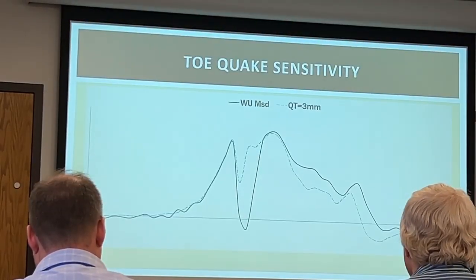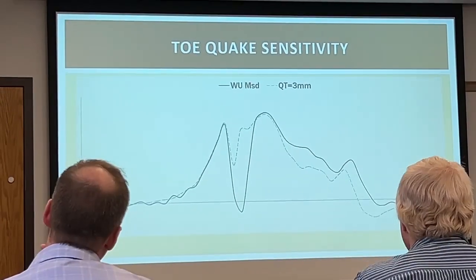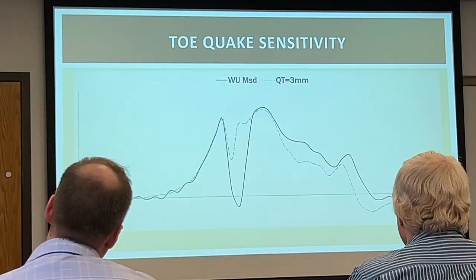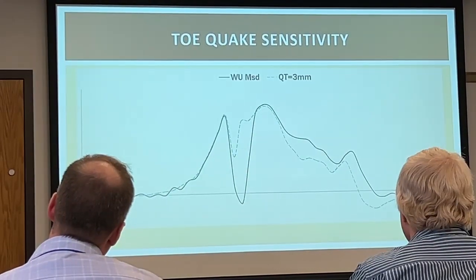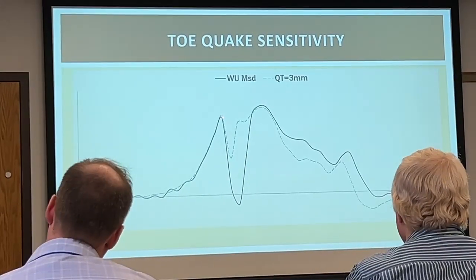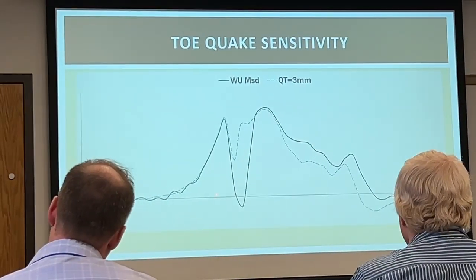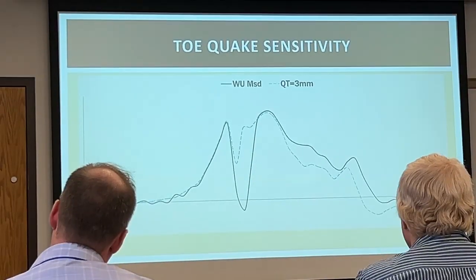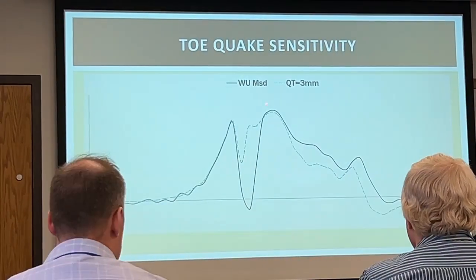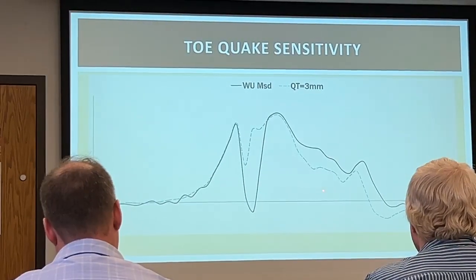So if we are looking at a wave up, remember, quiet period is either the initial impact or the part that's not in soil. This part is our indicator of shaft resistance. That peak is where the toe response starts to come in. That deep tension response is the pile toe moving significantly like a free end condition. And then we see a strong reflection that comes at 2L/C after that from some end bearing.